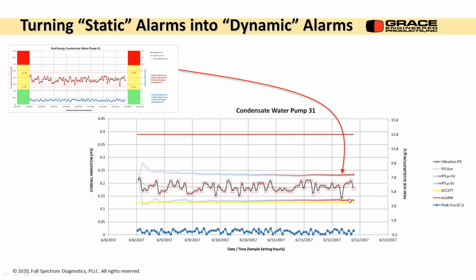And this is only 4 days. I think it's something that's phenomenal for just basic vibration monitoring. You still need to get a spectrum and a waveform, but it's telling us a lot more than we think it is. And I was just using basic statistics and having them update every hour, and it gets a really nice trend.